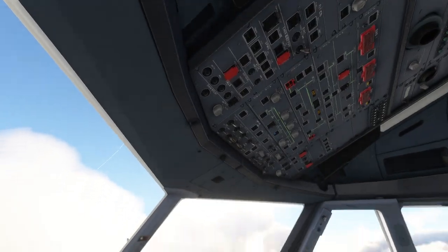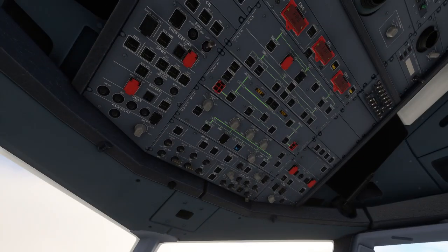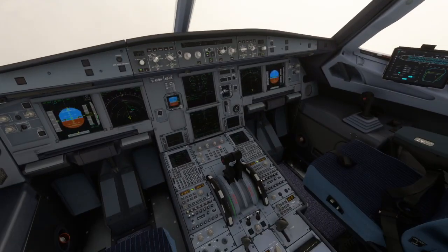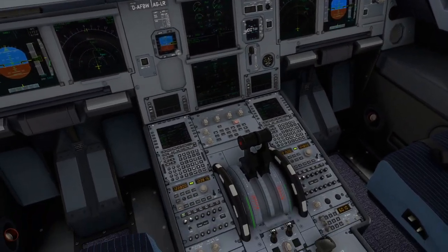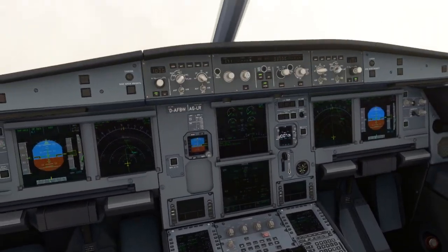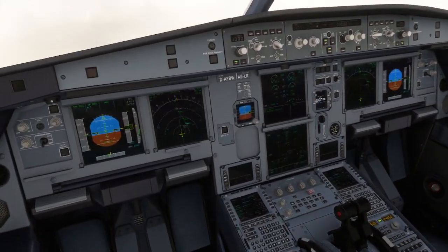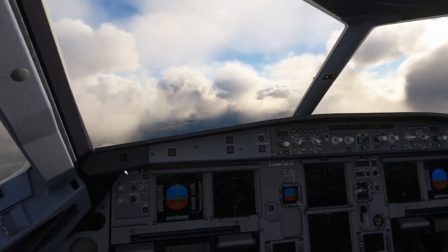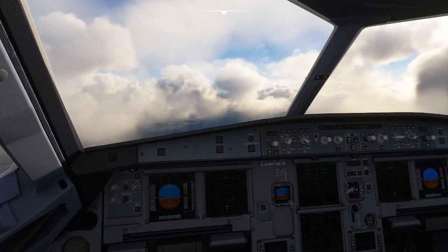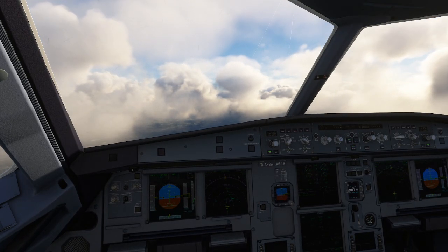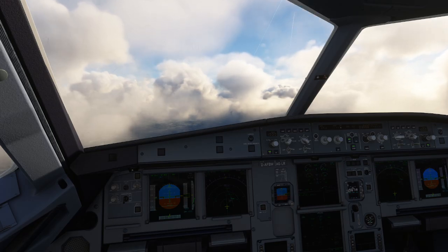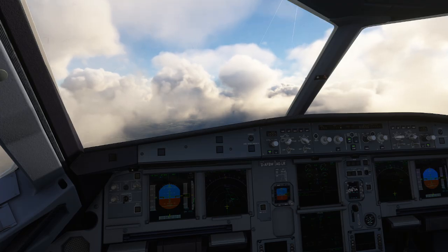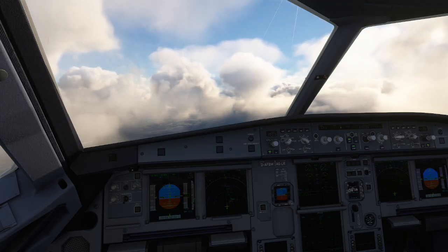So our aircraft is fully configured, and we have done the landing checklist. We don't have any ECAM messages, so we are good to land. After landing, we need to be mindful of where we are going to exit. So let's review Brussels airport information. When it comes to Brussels, we are landing at runway 27. After landing, we can vacate to the left.